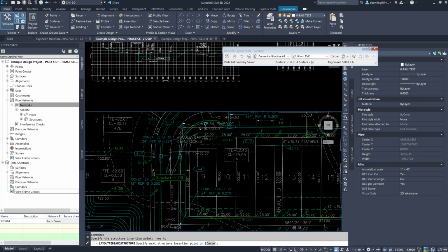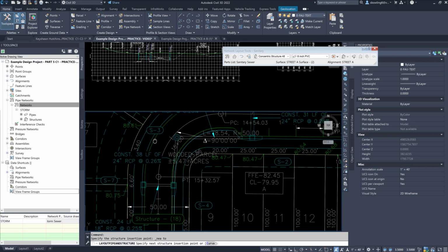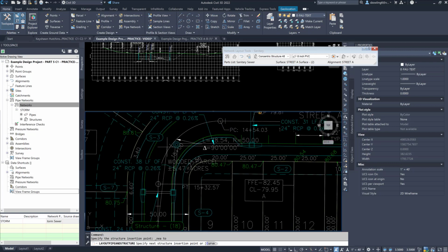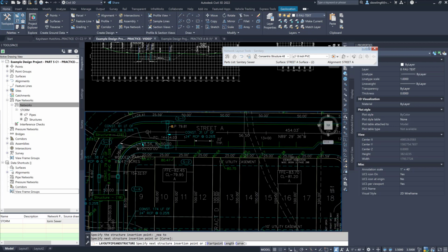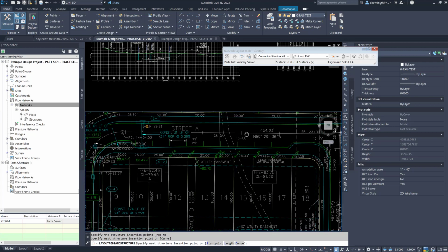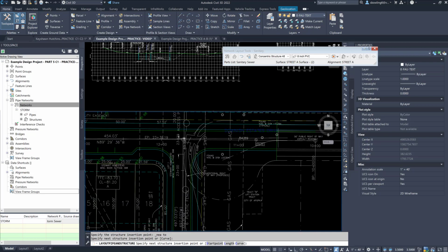So there's one manhole. Now, you can't put them outside an angle, so I'm going to have to end up using multiple manholes. So I'm going to go ahead and extend this because I don't want to cross this one. So I'm going to put it in the grass area up here. Okay, that's the second manhole. Now, the next thing that I have to do is you can only go 400 feet. So I can already see that there's 1, 2, 3. I may end up having to put in an additional manhole.